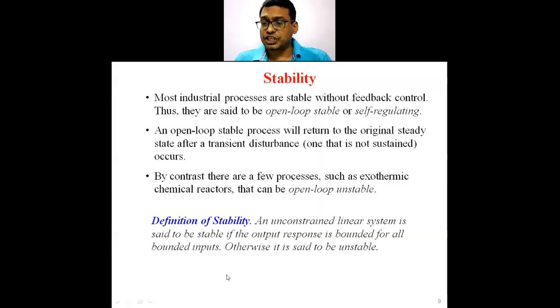Now the selection of these values for the gain, or proportional sensitivity of the controller, is important for the stability of a system. Similarly, non-oscillatory processes may exhibit oscillatory behavior with the proportional integral controller because of wrong selection of the values of the gain and the integral time constant.